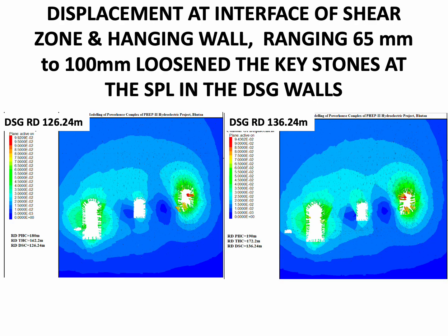As discussed in the earlier slides, due to the presence of the steep shear zone and the multiple sets of joints which were filled with crushed material, the rock mass lying in the hanging wall side in the rock pillars in the downstream surge gallery stood widely yielded. These widely yielded rock pillars were supporting the crown in the downstream surge gallery. This distressed rock mass in the yielded rock pillars was undergoing increased displacements with the increase in depth of excavation in the downstream surge gallery.